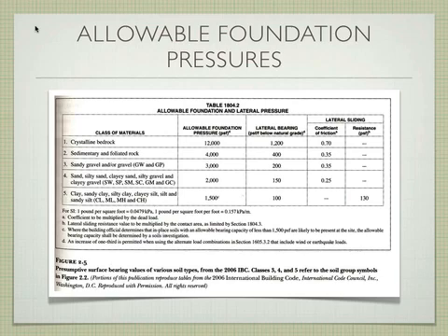So if, for example, you were in San Francisco and you wanted to build a skyscraper, what soil do you hope you have? You totally hope you have bedrock. There are a whole bunch of tricks when you design the foundation so that you can actually build heavy buildings in these other types of soil. But if you can find bedrock, that's always the best. And we're going to talk about ways that you might be able to get bedrock even though there's a lot of distance between where the surface is and where the bedrock is.